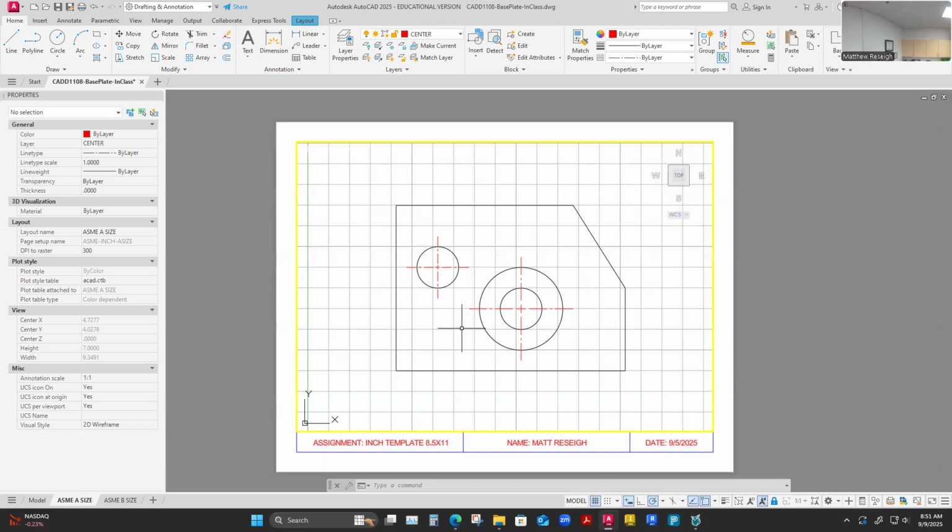Always remember that the default is 0. So you can always go back to 0 and reevaluate it and see if it's good or if I need to adjust it. So, long story short of that is adjust line type scale last, after your drawings are fit and most of your details are done. It's one of those finished things I do before I send to print or make my PDF. So right now I'm ready to make my PDF. So let's do it. Control P.